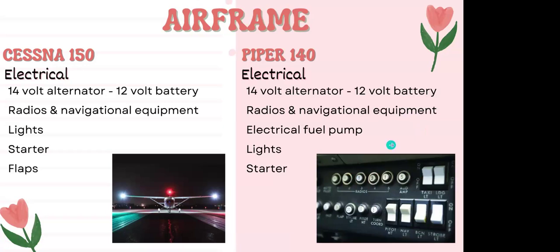So, for example, there may be a circuit breaker for the strobe lights specifically. So you may have very good charge from that alternator, good power from that battery, and you pop that strobe circuit breaker, you don't have strobes anymore because you are choosing specifically to cut power off to that one piece of the system.